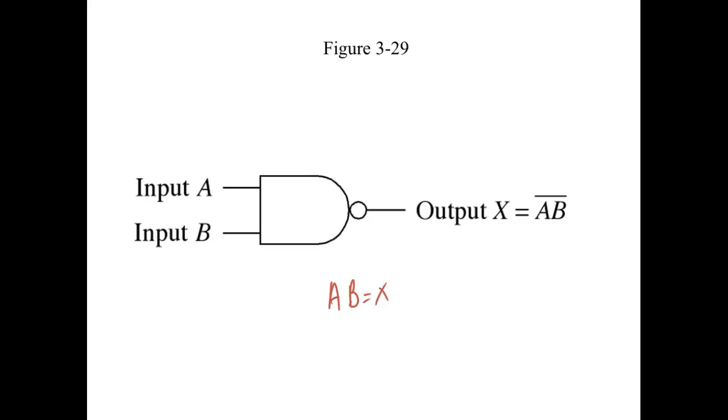But mathematically, that's incorrect, because what you're solving for in a math equation is always on the left, right? You understand? So we put the output over here, and then we put A, B. And the way we represent a low active output is we put a bar above both of them. So a bar above both of them means that the output is low active.